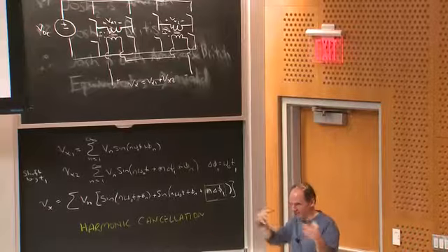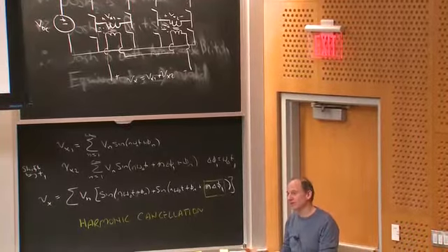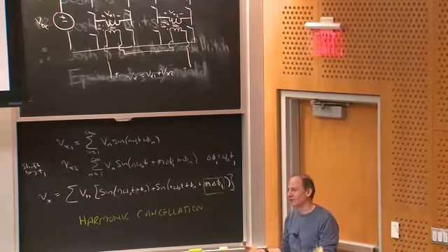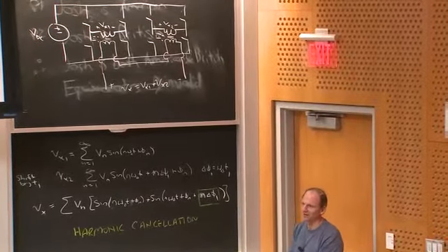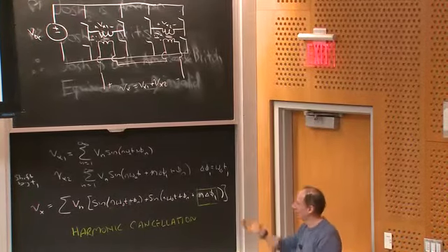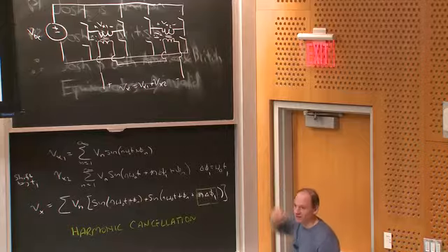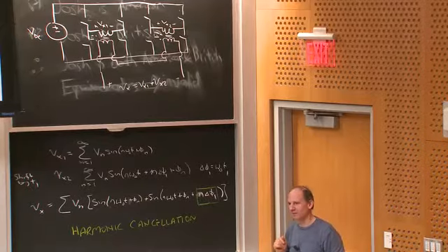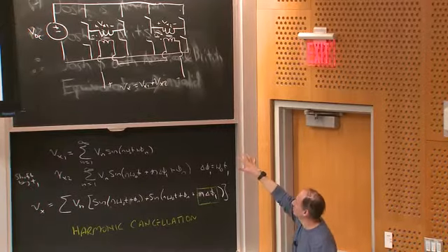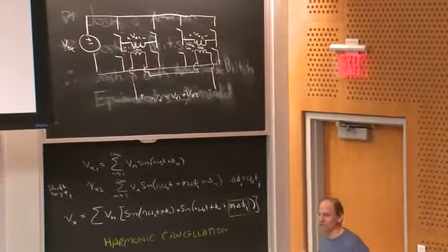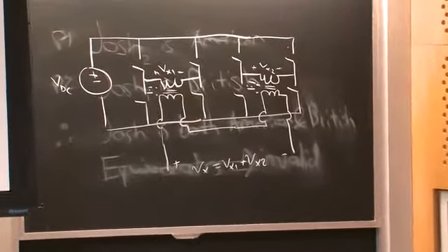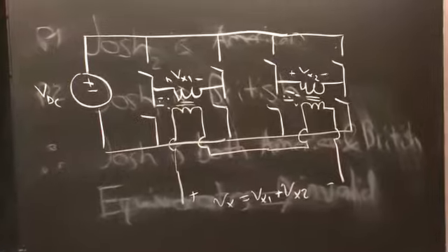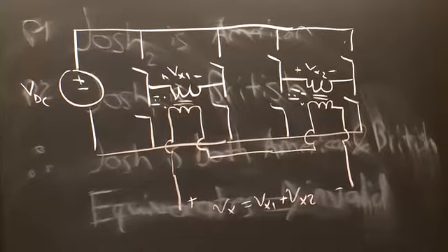We will see next class other circuits whose benefit is that, for a given input voltage, they use lower voltage switches to get the same output. So there's a lot of ways you can take advantage of the complexity you inherit. The downside to this one is principally that I have transformers that are rated for the frequency I'm outputting. In some cases I might not like that, but there's other circuits that get around that.